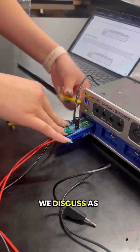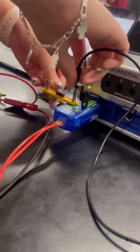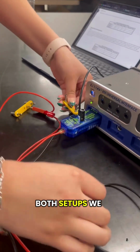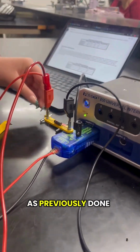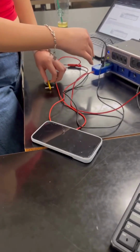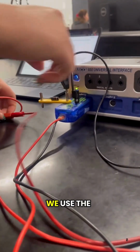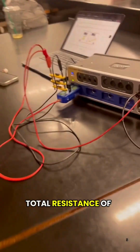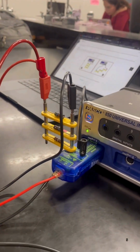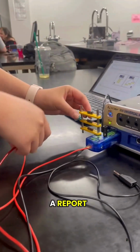Before taking measurements, we discuss as a team which configuration we think will have the greater total resistance and why. We then test both setups. We start with the parallel connection, increasing the voltage gradually from 0 to 10 volts, as previously done. We record voltage and current each time, repeating the same process for the series connection. We use the slope of each voltage versus current graph to determine the total resistance of each configuration. Again, we screenshot each graph for our report.